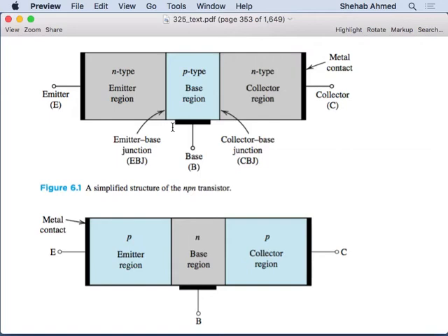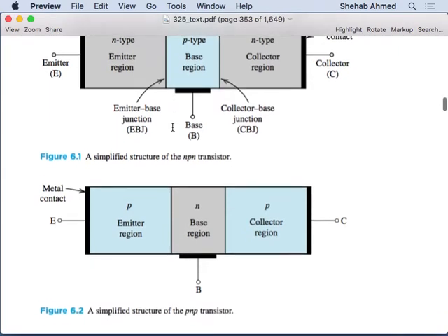This device, you will get confused, because the saturation region in the MOSFET was the amplifier operating region. Here it's called the active region. And the triode region there is called saturation here. And then of course cutoff is cutoff. So the terminology is a little confusing.